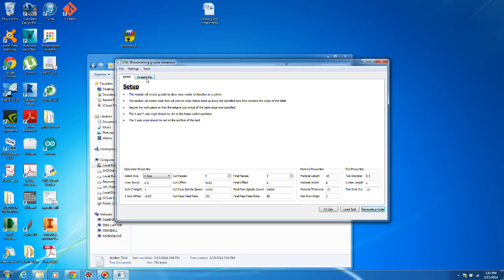In order to use this tool, you really should know the basics of G-code and how to interpret what's going on, so you're not surprised about where your machine moves. And at this point, I would really check that just about every time you use it until you get really comfortable with it, because otherwise it's easy to crash your machine, and definitely operate your machine safely.